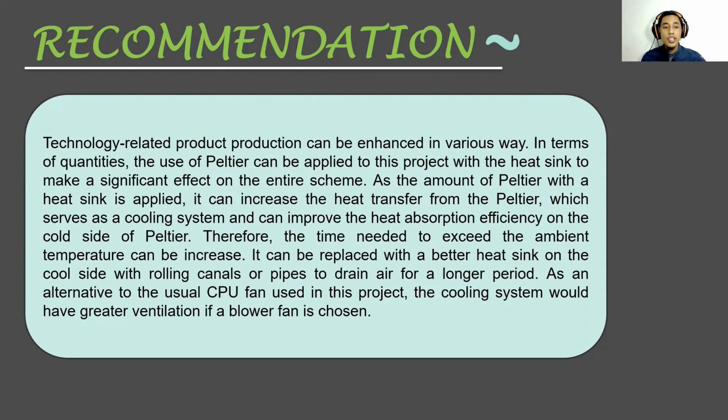As the number of Peltiers with heat sinks increases, it can increase the heat transfer from the Peltier, which serves as a cooling system, and can improve the heat absorption efficiency on the cold side of the Peltier. Therefore, the time needed to exceed the ambient temperature can be increased. It can be replaced with a better heat sink on the cool side with rolling channels or pipes to drain air for a longer period. As an alternative to the usual CPU fan used in this project, the cooling system will have greater ventilation if a blower fan is chosen.